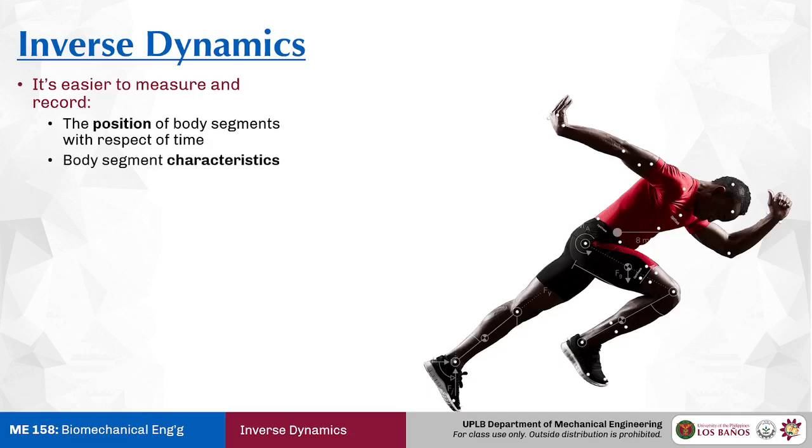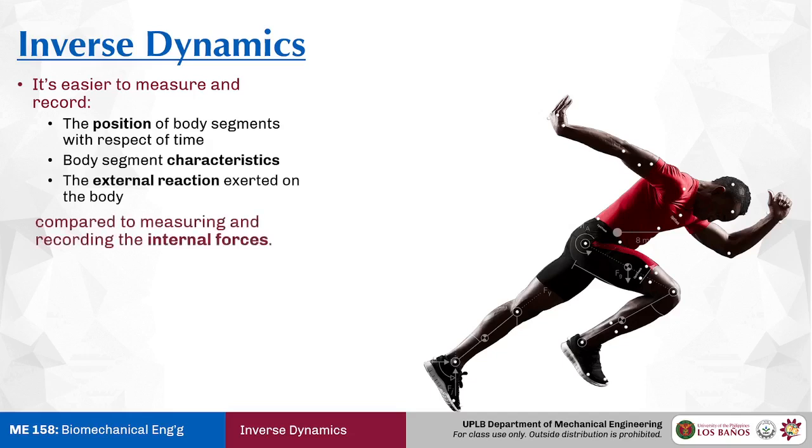It's also easier to just do some body segment characteristics. Well, when I say easy, it's quote unquote easy. There's a lot of things that went through this. And third, it's also easier to just measure the external reactions exerted on the body in comparison to just measuring the internal force. So that's why it's called inverse dynamics.